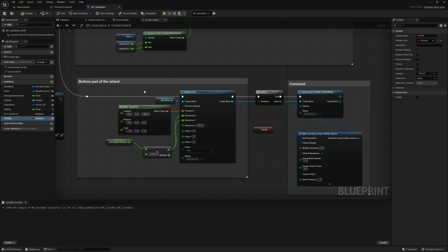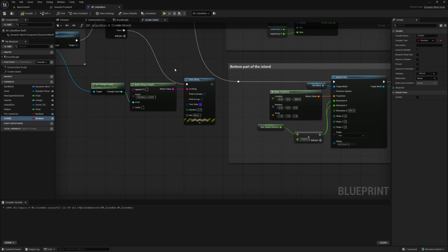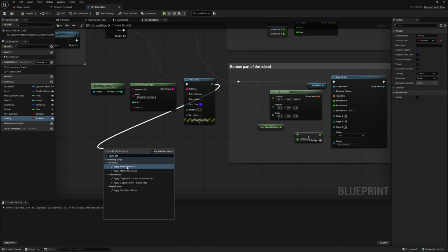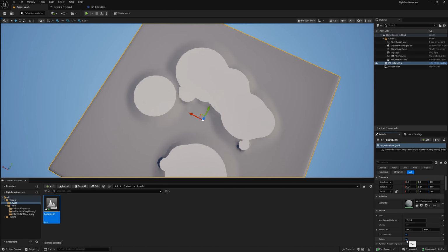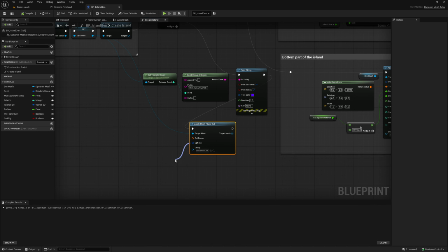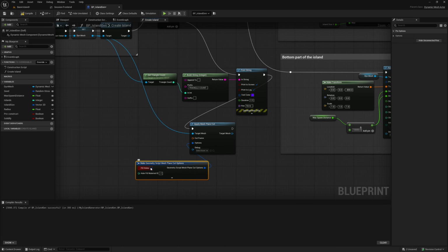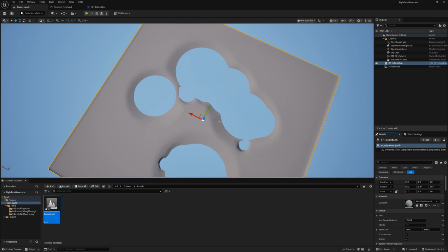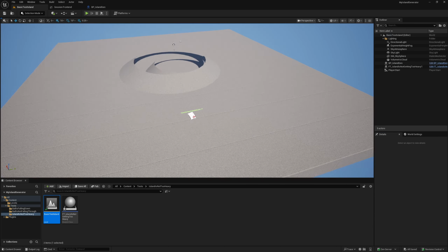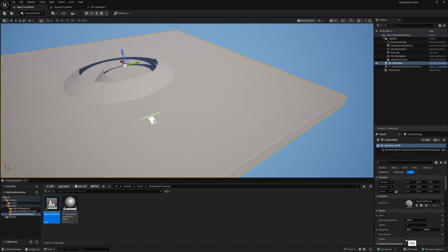A second thing I would like to show you: after the print, I am going to apply a mesh plane cut on the dynamic mesh. I think the default values are fine for now. Let me show you. But I want to see inside. So I need a make options node to uncheck the fill holes option. As a result, I can see all the geometries inside. And when I solidify, all the internal cones are gone. So, on the functional test level, when I solidify, I can see that I don't have other cones inside.